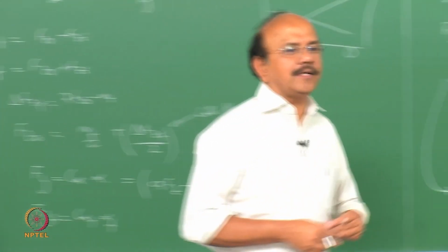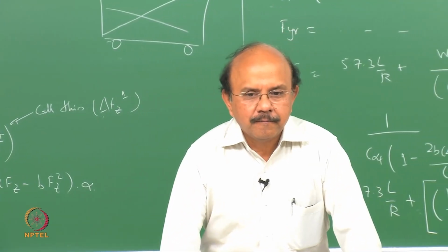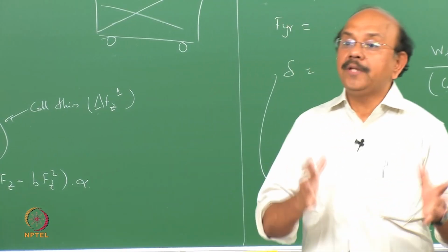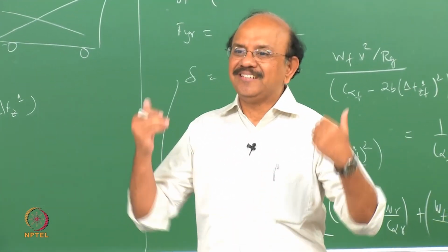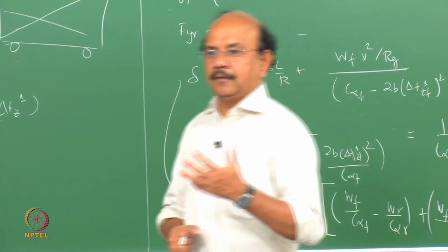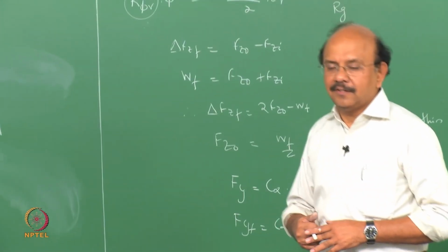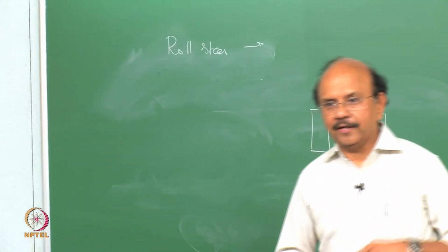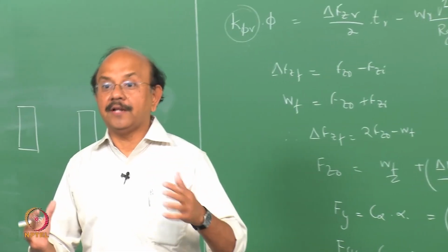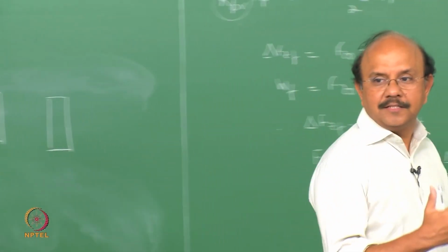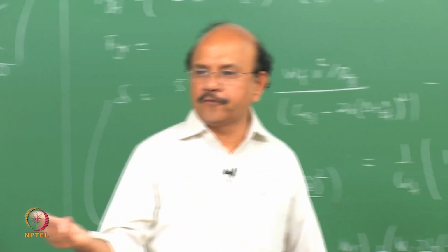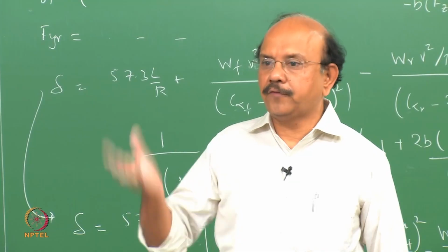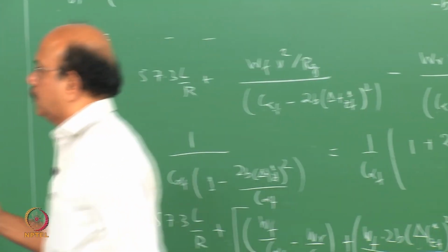Okay, that's a better question for this course. Yeah. One of the concerns of people who design vehicle dynamics is how many of these factors change dynamically. For example, the roll axis, does it change? Designers ensure that this does not change. Okay, roll axis does not change, roll centers do not, they want to ensure. So they would look at this dynamically, okay, either in a software like Adams or one of them, okay, or they will measure it. So many of them, they will measure it. You've hit the correct point.